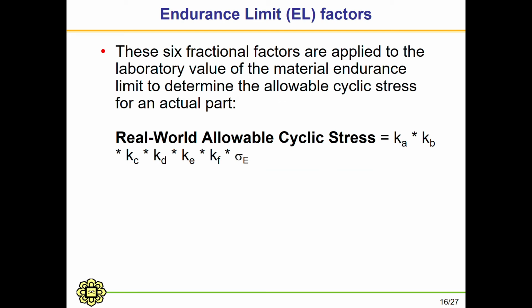These six fractional factors are applied to the laboratory value of the material endurance limit to determine the allowable cyclic stress for an actual part.